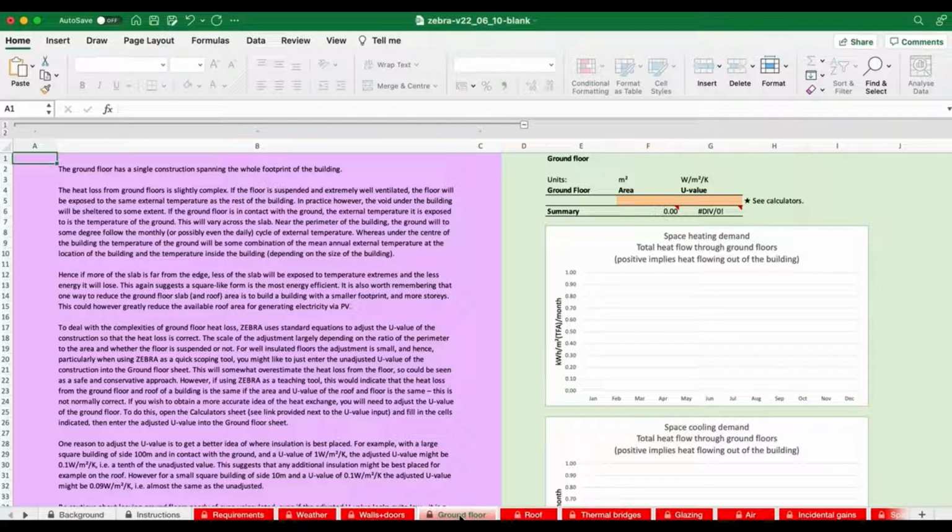The temperature underneath the building will be some function of the climate, but it certainly won't be the same as the climate. If you dig a hole in the ground and put a temperature probe down, say 3 or more meters, the temperature you normally get to is virtually identical to the mean annual air temperature of the location. And something like that is happening underneath our building.